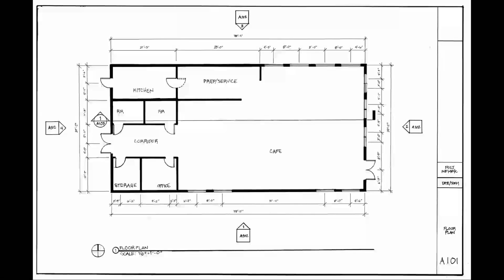But what I want you to do now is focus on sections, which are a little bit different than elevations. We're going to begin by discussing how to notate them on a plan view, and then how to create a sheet with sections on it, where we will look at the sheet layout and the annotations, and then we'll look at individual section drawings. So to start off, we're going to look at how to show a section on a floor plan view.